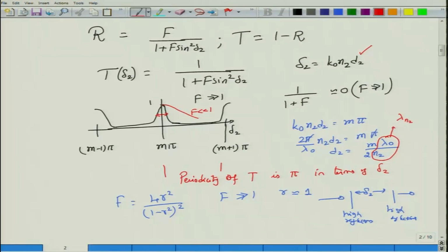I would actually ask you to solve this same problem not in terms of these matrices, but in terms of the transmission line analogy that we have already talked about. In this case the transmission line analogy is very simple. You have a film with the impedance of eta 0, which is the air impedance, and inside this film is captured as a transmission line with a distance d2, having a characteristic impedance of eta 0 divided by n2.